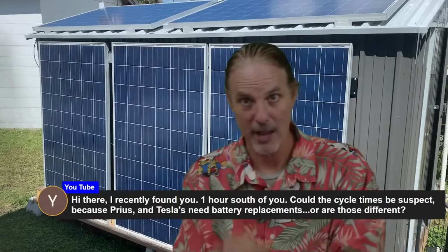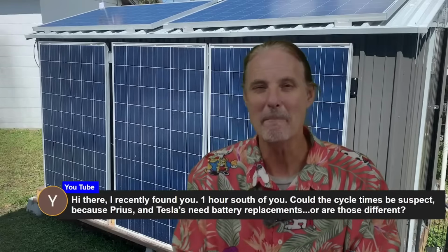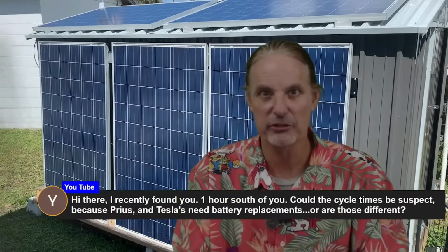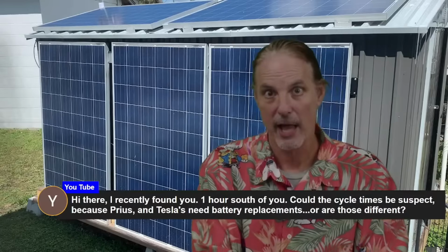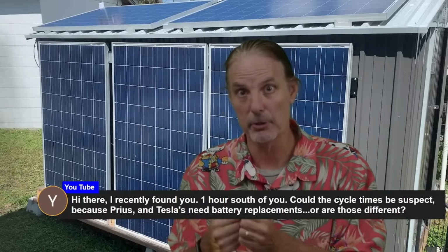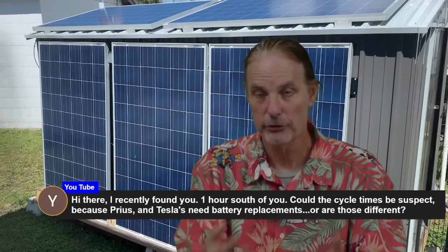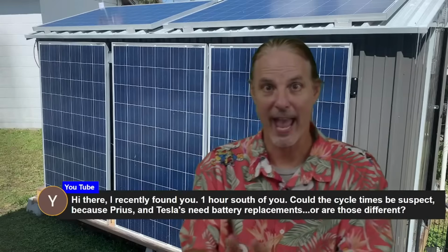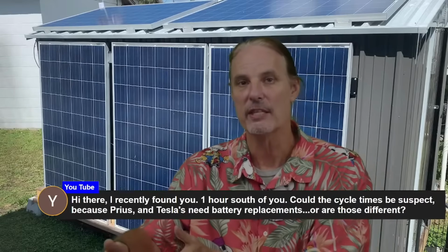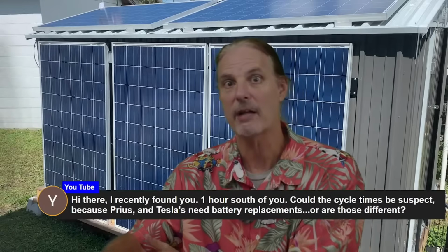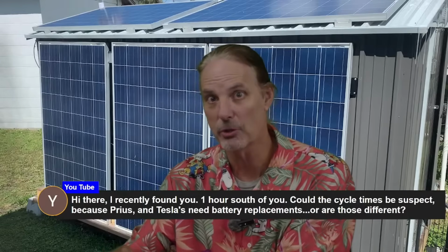But there are also some downsides. The consumption or charge rate is not as much. You can't charge it as fast. It doesn't absorb the power as quickly as a lithium battery, as opposed to the lithium iron phosphate limits your ability to charge it. It also limits its ability to discharge. So in essence, what you basically do by adding that is you extend the life of it, but you decrease the amount of energy that it can hold, the speed at which it can take that energy in, and the rate at which it can discharge.